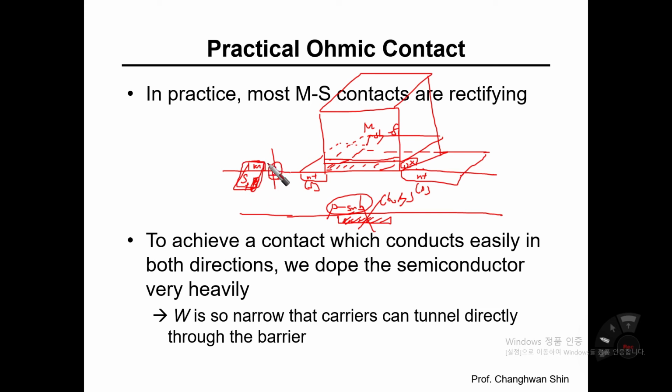For that purpose, the semiconductor part right below the metal should be very heavily doped. Once the contact pillar has been formed, right below this part should be very heavily doped. Then your body biasing can be applied and delivered through this pillar-type contact.